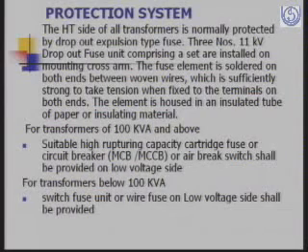So usually even if we put an MCB and MCCB, then people tend to put something inside the MCCB to hold it in place so that it doesn't blow off. But it would be a better practice to install MCCB or MCB on the low voltage side to protect the distribution transformer. For transformers below 100 kVA, some switch fuse unit or wire fuse is used on the low voltage side.